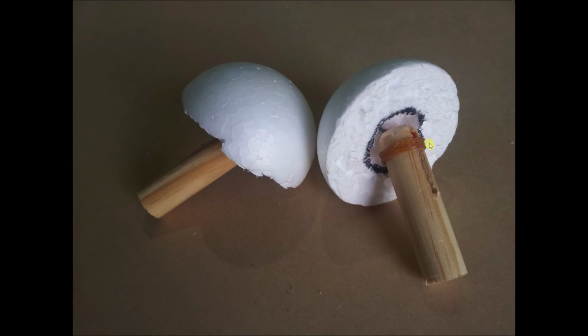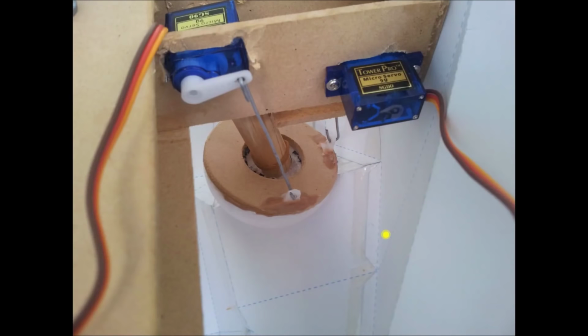You can see the rubber band on the eye stalk here. That just allows it to hold the 2 halves of the dowel together, provide a slight amount of friction there so that the eyeball isn't wobbling around completely unrestrained. Here we see the back of the eyeball. It's a disc of 3mm MDF glued to the polystyrene, along with some cut down servo arms. Each servo came with 3 servo arms, so I had plenty to spare there. The connecting rod is just 1.25mm wire, and it's just run and bent around between one servo and the control